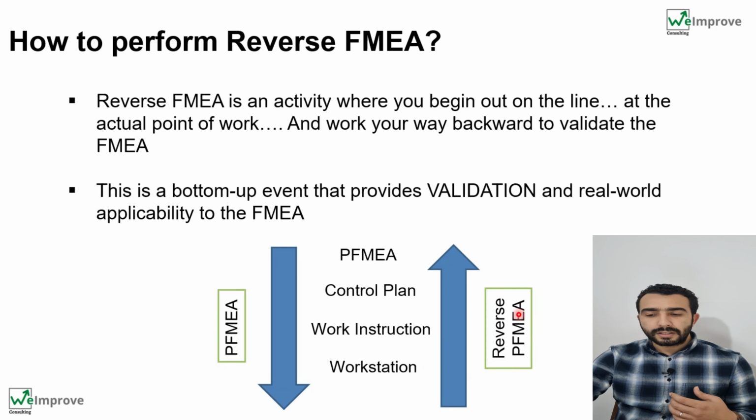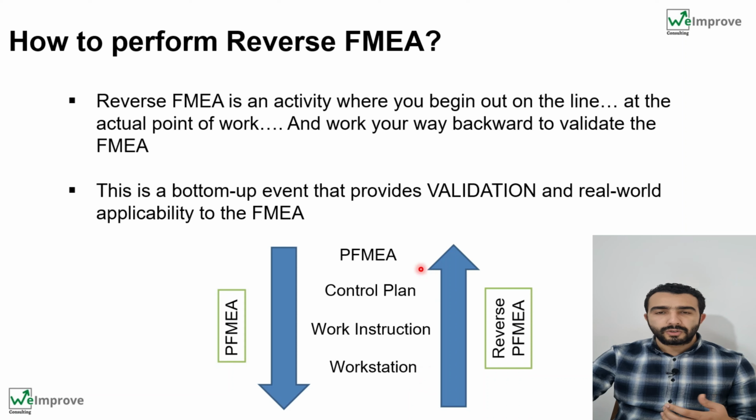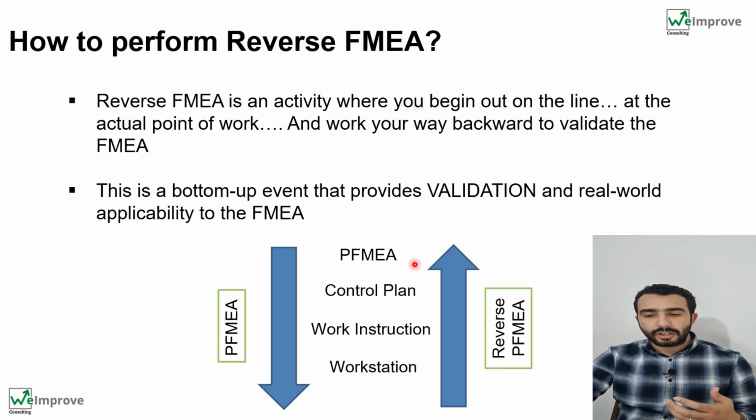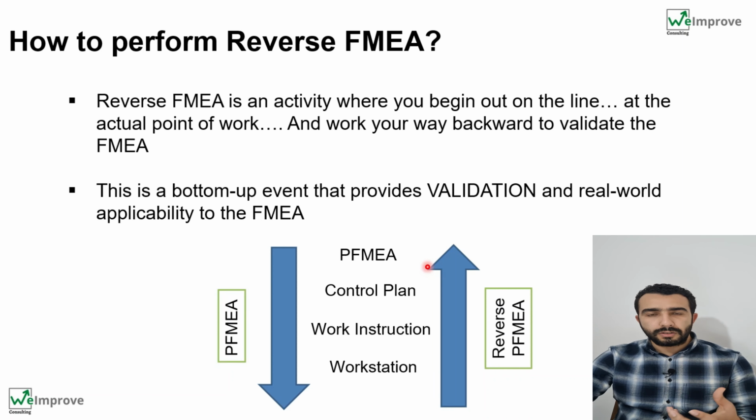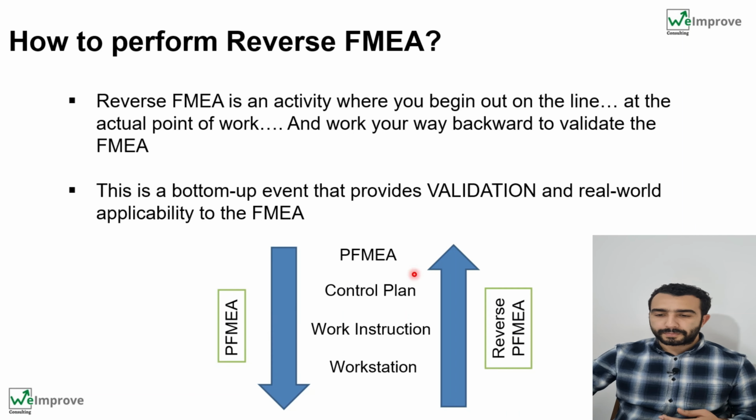But regarding the reverse FMEA, you are starting in the opposite way. So you are starting from the workstation, you are checking all that's happened, then you are going back to update your documentation in case you find out any potential risks or potential failure modes or any errors or gaps. So for this reason it's called reverse, because you are doing it in the opposite way of the PFMEA.